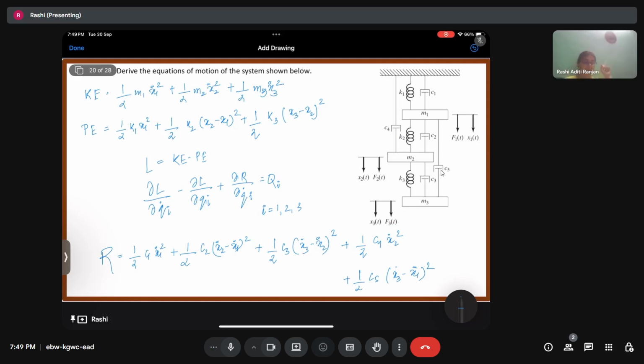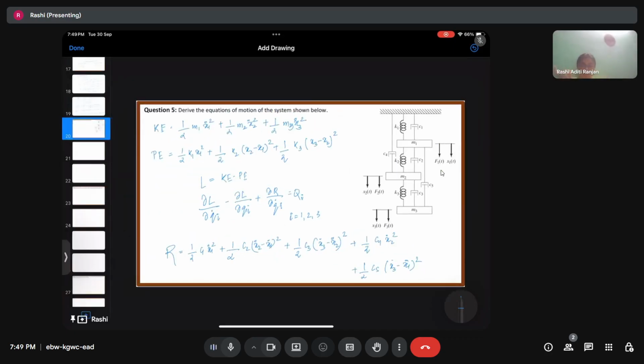Now, what is important to note is that this is a damped case. So here, the contribution of natural frequencies is going to be 0. Why? Because the natural frequencies appear in the transient phase. In the steady state response, every transient amplitude damps out with time. The steady state response is just energy given in by the forcing and excess energy leaving through the damping, and the system is going to vibrate only at the frequency omega.